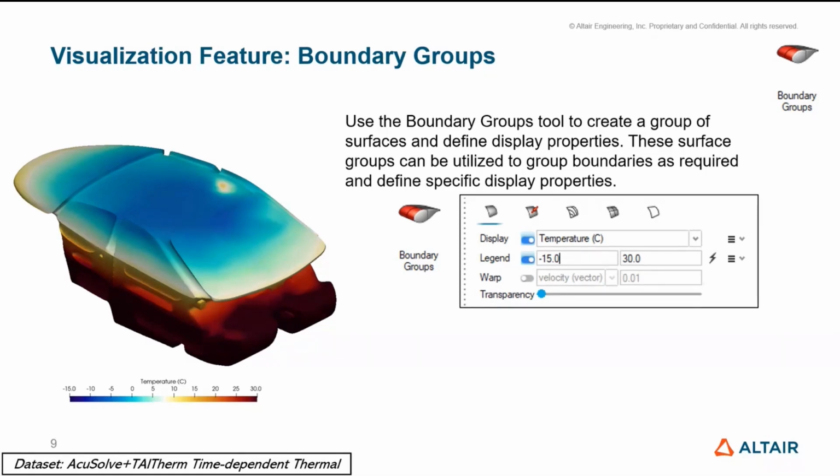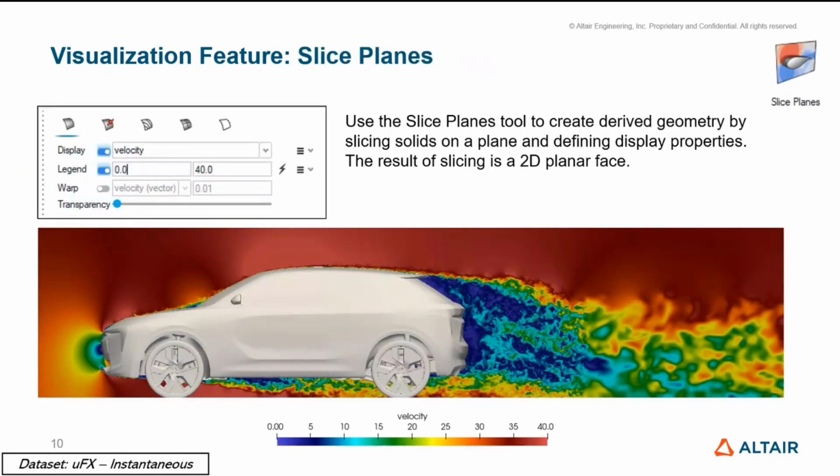In this case, I do have a derived value here, and that's temperature in Celsius. I computed this using the calculate tool, just subtracting out the 273.15 to go from Kelvin to Celsius. I have access to that variable on the boundary groups once I've predefined that. Here we're just demonstrating that we can have a boundary group and color it by temperature in that derived contour.